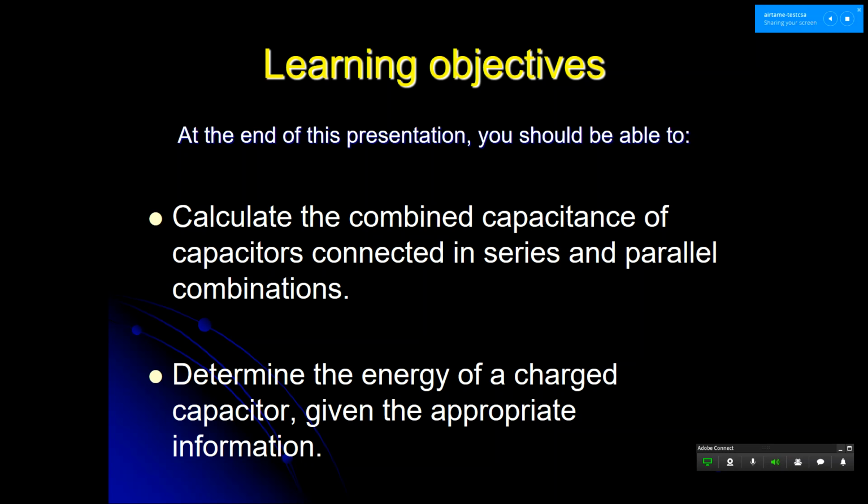Defibrillator. Maybe not so much where they're located, but why they're used is because they can provide a higher impulse of charge in a shorter amount of time than the current from an outlet. An outlet is only going to provide you with a certain amount of charge in a safe quantity, whereas you might need a huge burst in time. So a defibrillator, for example, can deliver a huge amount of charge in one moment, but it's just getting electricity from a regular power outlet, right? And the way it does that is that it accumulates the charge and then discharges it all at once.